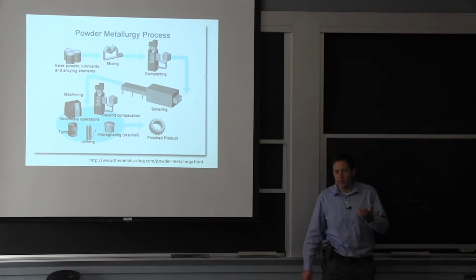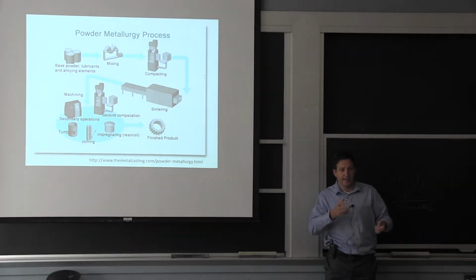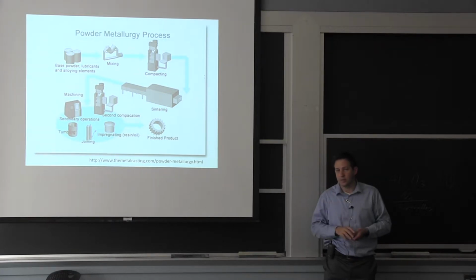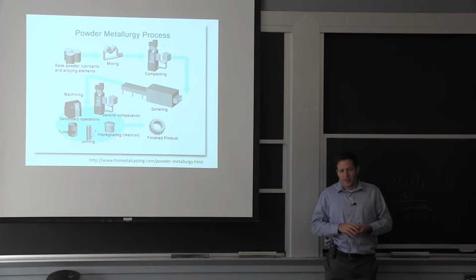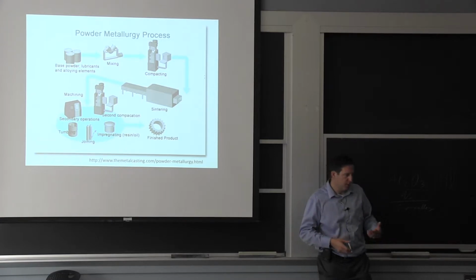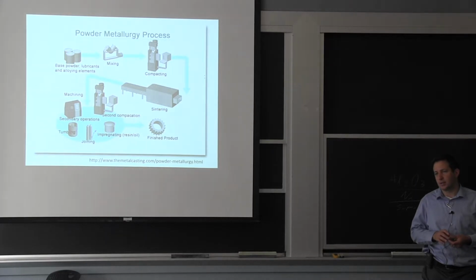And you didn't really get the opportunity to use deformation to close these voids and use diffusion to heal everything. So if there's a contaminant, a particle that is not the alloy, say a little bit of oxide that came in with your incoming powder, which is not unusual, then you start with essentially a micro crack at that location. So we don't use these parts intentionally for fatigue resistance. You could still use it. It's used in gear, like I mentioned, but it's not really the best way to get ductility.